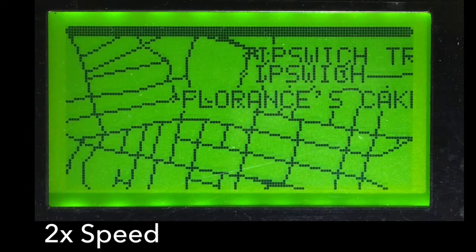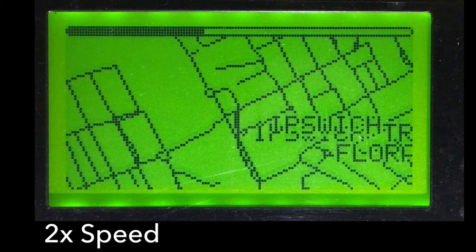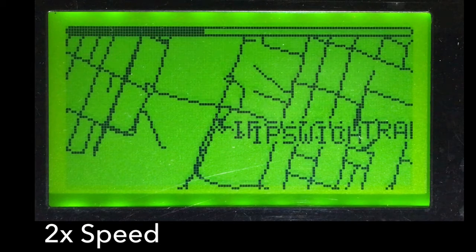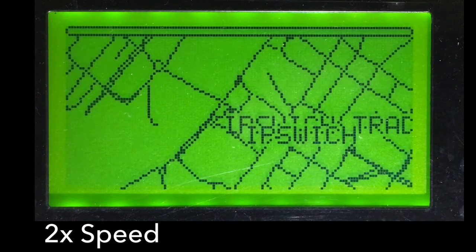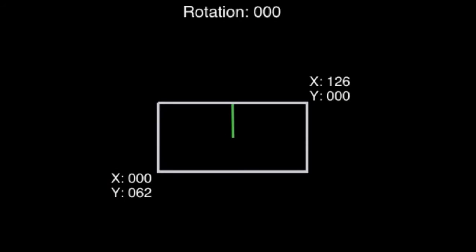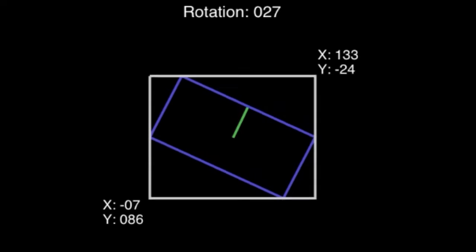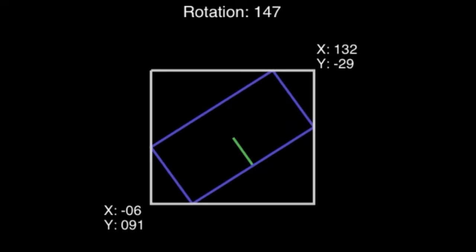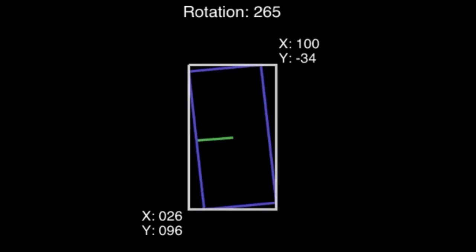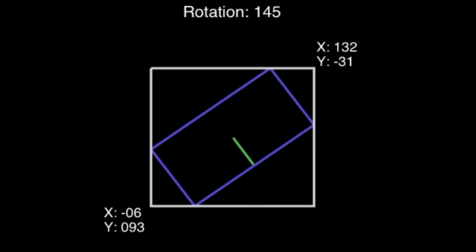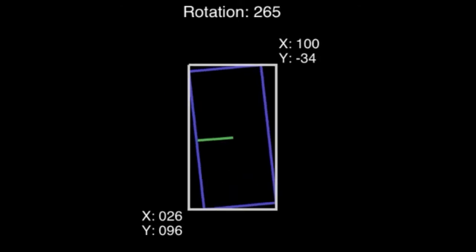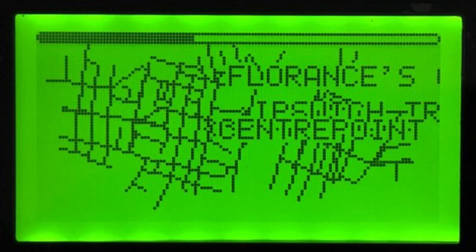There are a few ways that I've sped up the GPS map render. The track up mode will never be as fast as the north up mode because you still have point rotation. One of the ways was a change to the map file format, so there's actually less overall reading from the SD card. And the major update here is a dynamic clipping box. So given the current angle of rotation, the clipping box will be as narrow as it can be in either direction to make sure that the least is drawn as possible, speeding up the map render further. I say the least is drawn, but in track up mode, every point that's drawn has to also be rotated, and I think that's where the expense in CPU time is.